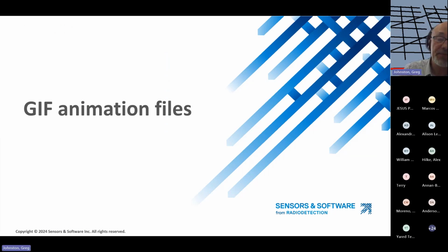So that's actually my favorite new feature of the EKKO Project software. I think it's going to get a lot of use. I think people are going to like using it because one of the things it does is if you can see the target that you're interested in a depth slice, you can draw it very quickly and you don't have to go through all those parallel cross sections and add individual points to the hyperbolas. So it speeds things up dramatically.